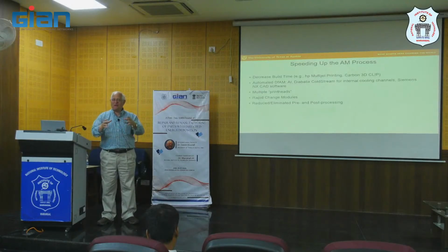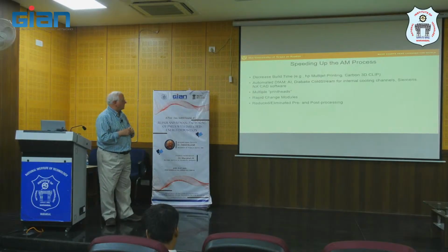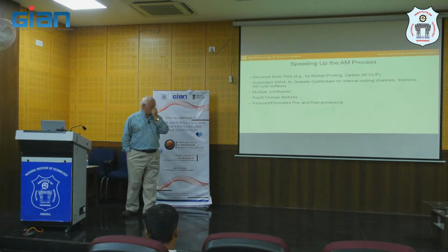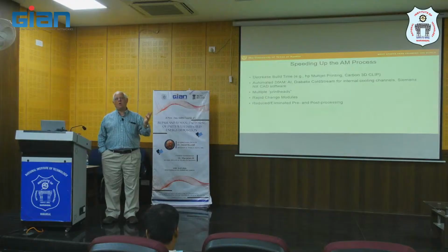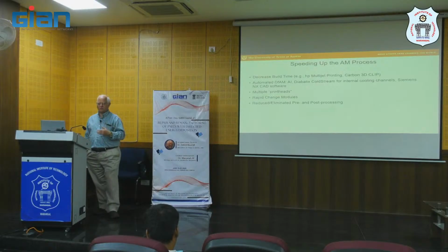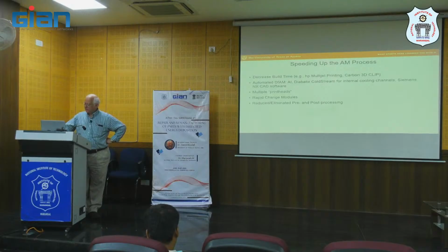With powder bed fusion, they have certain machines where you can pull the entire build volume out of the chamber, slide in a new one, load up the powder beds, and be ready to go very quickly. So these again are ways to try to accelerate the process. And then there are approaches for eliminating or minimizing the amount of pre-processing or post-processing that has to happen. So all of these are geared towards getting parts out the door more quickly.